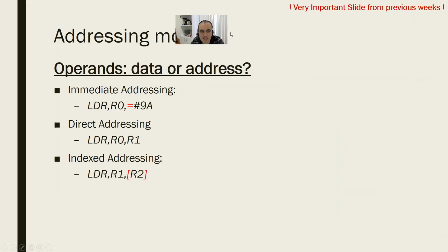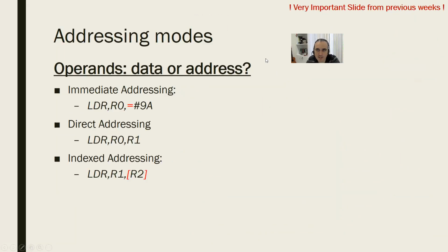So guys, actually, I've used STR and addressing modes. We have to remember this. So guys, when we used LDR, we could use 3 types of addressing modes. This was LDR. Actually, this operation had nothing to do with the memory. You are saying in the code, hey, microprocessor, write this value to R0.